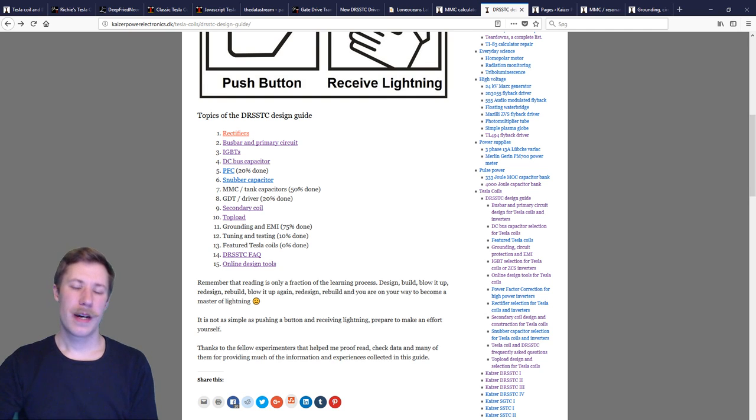Now rectifiers, you should read the chapter. You should understand the concepts of how to rate them and how to run them in parallel and so on. But there is no real magic going on here. It's simply a matter of dimensioning your components right, and again ensuring even current paths. That is again overall the number one design criterion here.